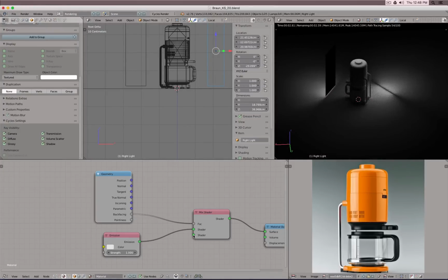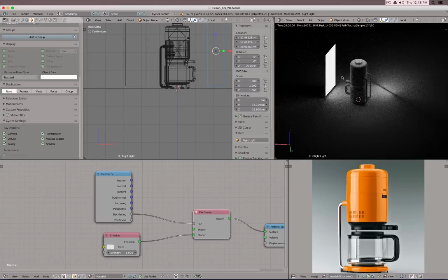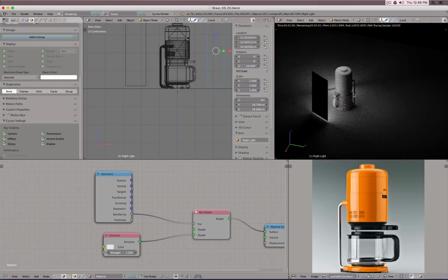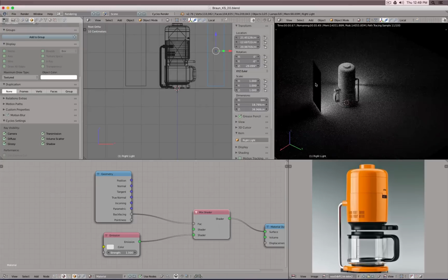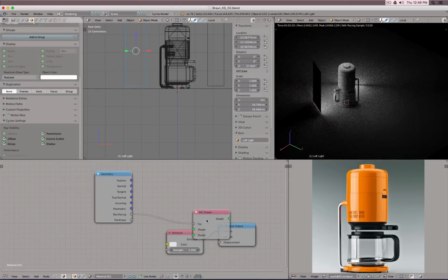And the back facing, for example, should be black. So see, this is front now, this is back, because we say the back facing. And if I flip this, now you can see the back of my object is black, and there it emits the light. Because we can select one mesh and give each side actually a different material. That's the way how you mix between two different materials by using the geometry as the mixing factor. So we can do the same actually to the other mesh there, paste it in there.